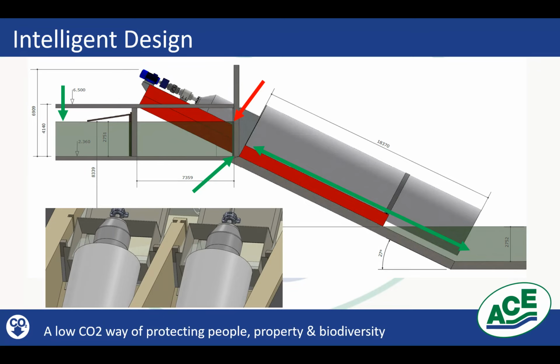That means that with an open screw system, the red arrow on your screen is where the bottom of the screw has to be. Now with our system, because it's enclosed, when the brake is applied to the shaft, there is no way for that water on the outfall level to slip back through the screw in the trough. This means we can reduce the overall height of the screw so that the output, or the bottom edge of the screw, can be where the green arrow is, underneath the red one.